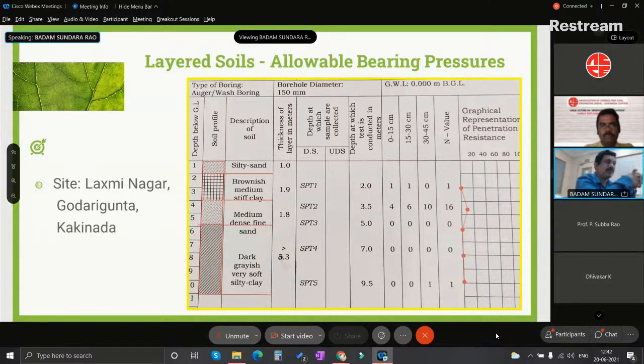Why? Because we are considering soft clay. The soft clay bearing capacity is not more than 2 or 3 tons per square meter, at most 4 tons per square meter. With an overlay of a sand zone of depth 2 or 3 meters, after deducting the depth of foundation of 1.5 to 2 meters, we have at least 1.5 to 2 meters of sand layer, followed by marine soft clay, that is, soft to very soft clay. That governs our bearing capacity also.